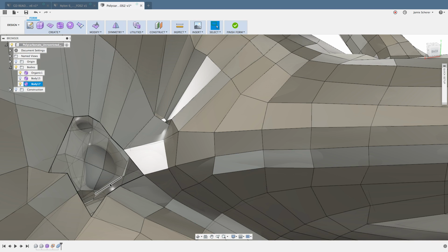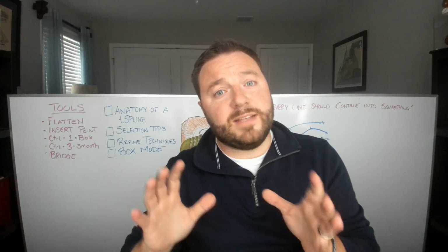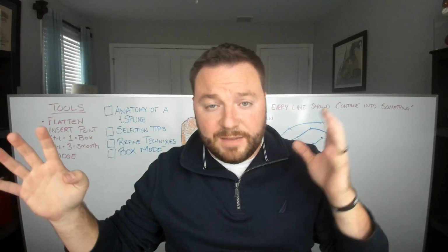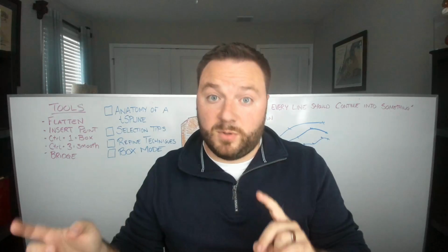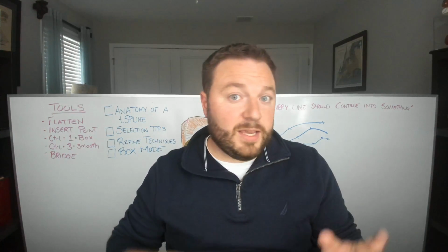The other thing that'll come in handy, if you have a scenario where maybe you have 2 faces on one side and 3 on the other, Bridge is always going to want to make you transition from the exact same faces on one side to the other, or multiples of one another. So 2 faces can bridge into 4, 3 can bridge into 6.